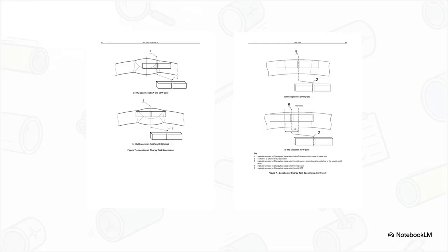And this methodology gets even more microscopic when we talk about Charpy impact testing, which measures exactly how much energy the steel can absorb before it just completely fractures. Here, location is everything. Depending on the spec, you have to precision target either the heat-affected zone, that highly stressed area right next to the fusion line, or the direct center line of the weld bead itself. Millimeters literally matter here. If your notch is even slightly off-center, your test results are pretty much completely meaningless.